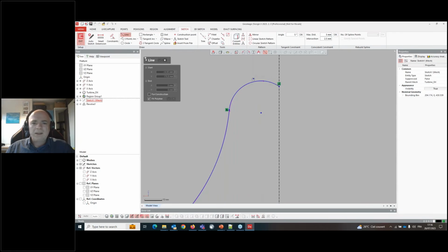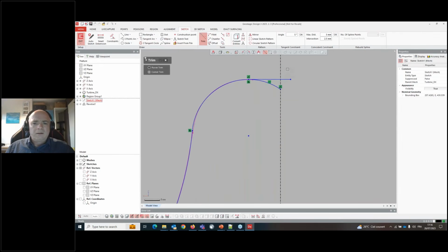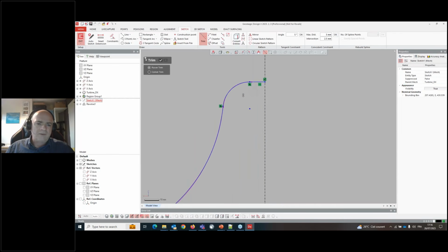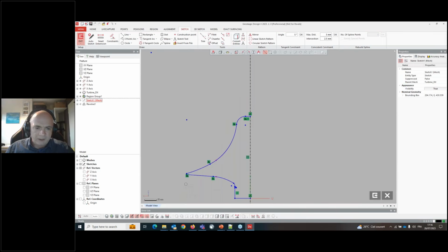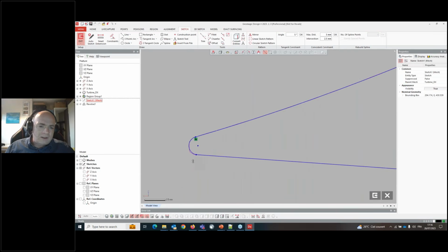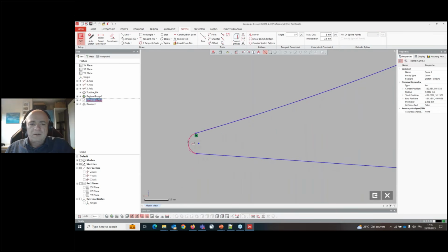The software didn't get any information there, so it continued the circle. I will just build here a line from here to there, tell the software that this line is horizontal, and then I will trim that in Power Trim. I will trim that and that just to get the connectivity. And also I'm just checking that I get tangency everywhere.